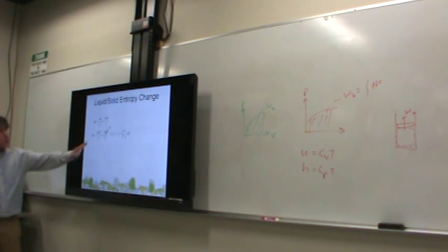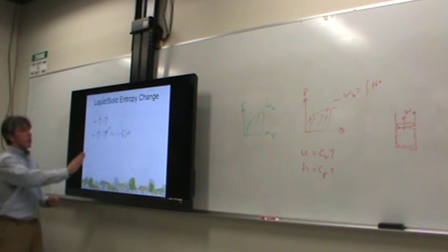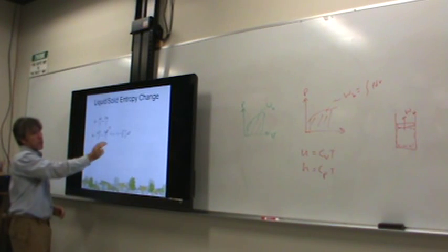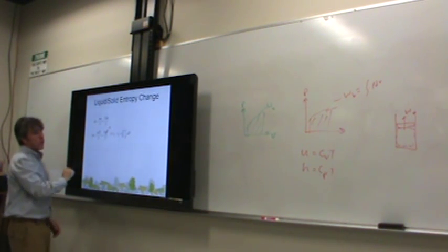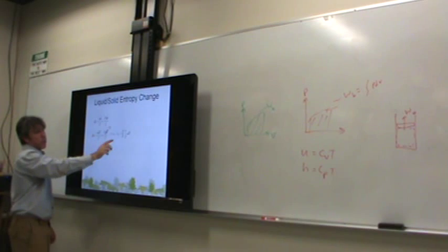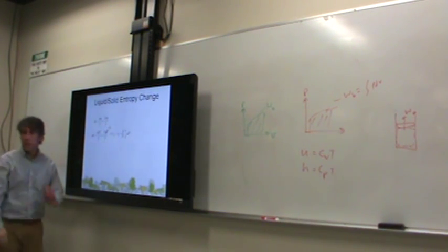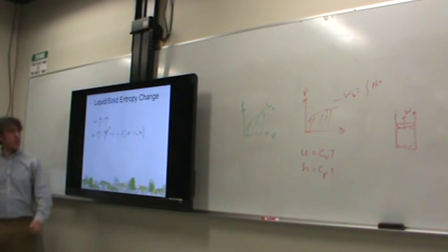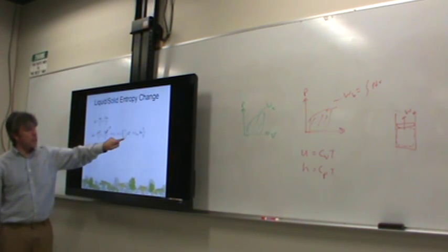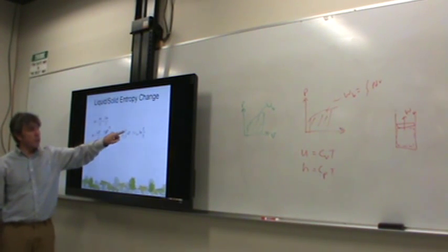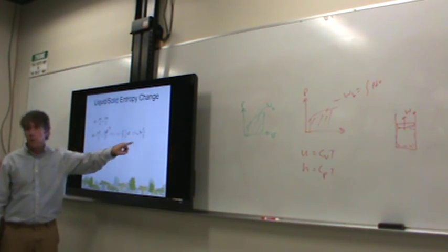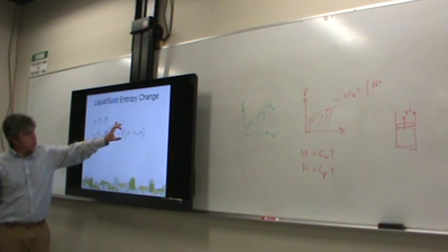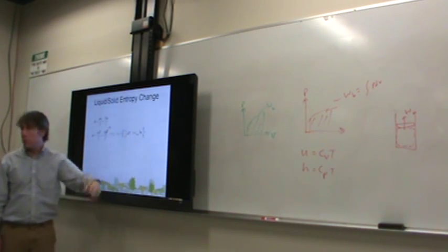So what we end up with, once we integrate this equation, how would we integrate it? Well, basically this term is gone. We'd have to integrate the entropy from one state to the next. We'd just get the change in the differential variable. We'd integrate this side from state 1 to state 2. We can't really simplify it any farther than this, at least not initially. If we could say that the heat capacity was constant and did not depend on temperature, then we would have the integral of 1 over T dT, which is just the natural logarithm of the temperature. And once you evaluate the natural logarithm of the temperature at the temperature limits at state 1 and state 2, this is what you would get.